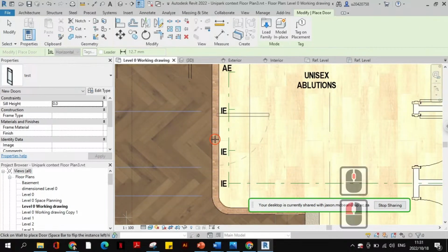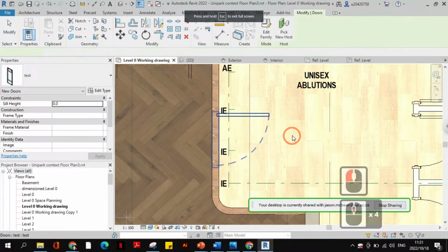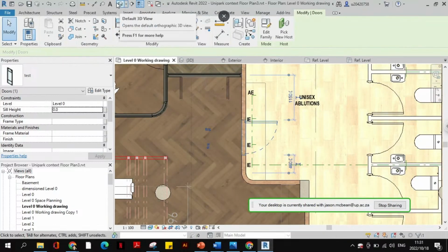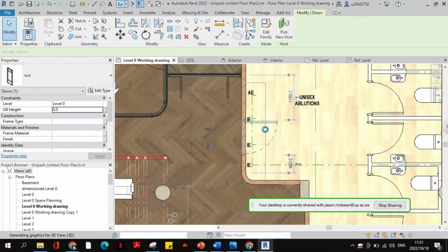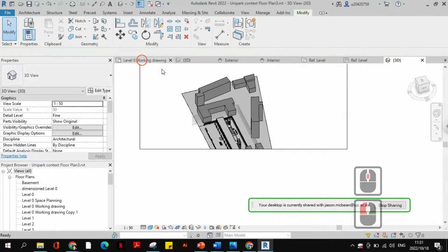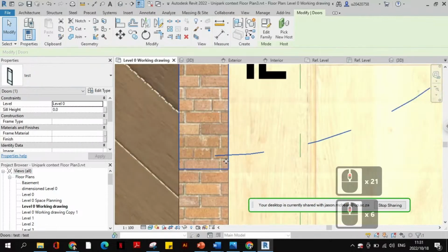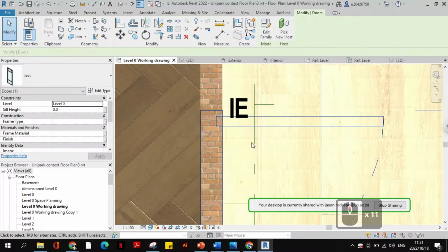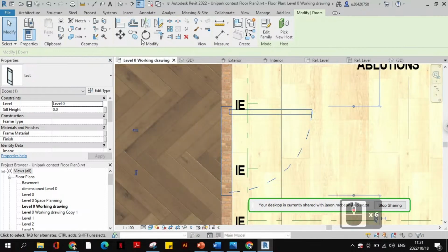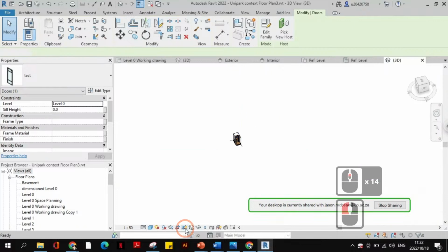So here's my little 900 door, and look at the symbology and look at everything. It will cut the opening in the wall. So let's just go to 3D view. The line weights are off. So in 3D view, select this guy quickly. I'll just have to draft in where the door frame goes as well. It's a rectangle. And you can put a masking region so it always hides things like the floor finishes, that type of stuff. So we all have to do that as well. Okay, but let me just quickly show you this. So now in 3D view, I'll just switch this off for now so you don't see that.